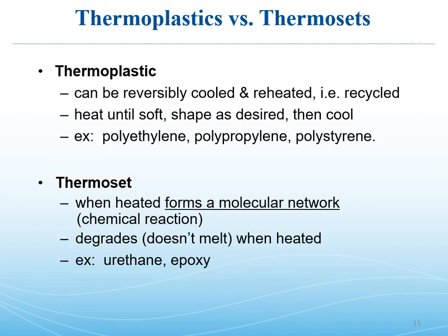That was one of four, with number and weight average molecular weight, polydispersity index, the ratio of weight average molecular weight to number average molecular weight, and then degree of polymerization being two definitions. One, the number of repeat units within a given single chain, or the number average molecular weight divided by the molecular weight per repeat unit.